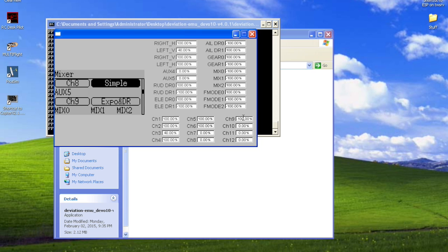So again, you can set those how you like them. I set them up to be all the way to the bottom, middle, all the way to the top. There's that, and the flight mode works exactly the same way as well. It's going to toggle 0, -100, and 100 accordingly. And then the last thing to check is my auxiliary 4. You see that's 100%, and that maps down here to 7. Channel 7 is my output there.